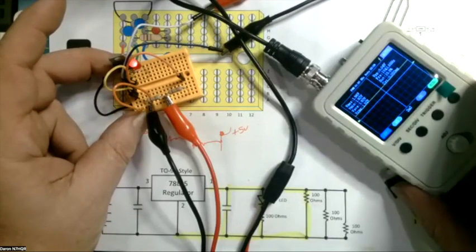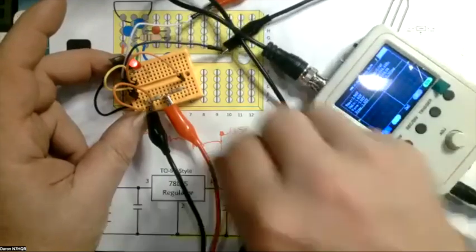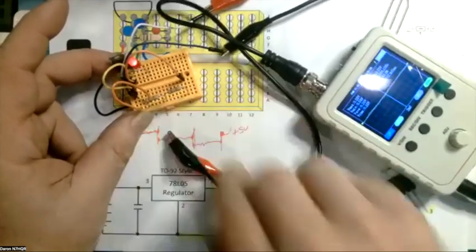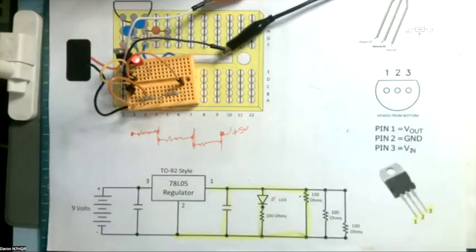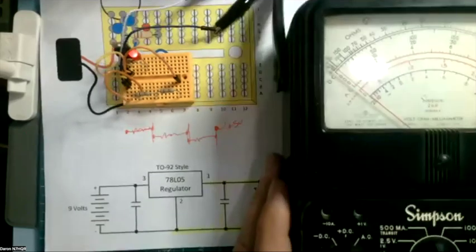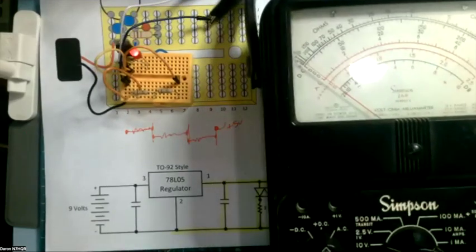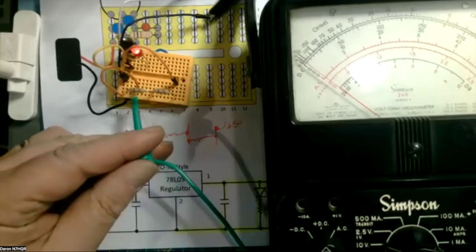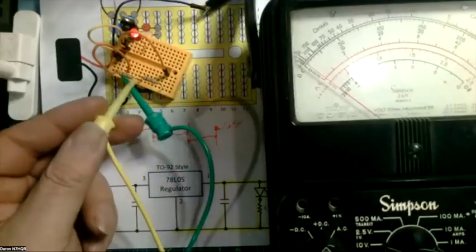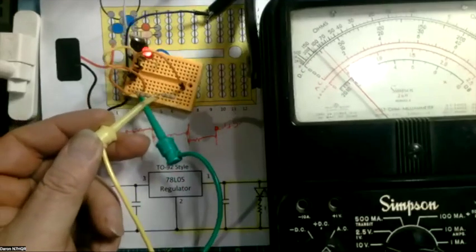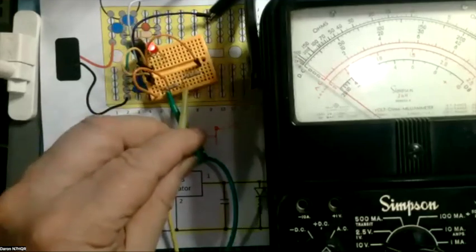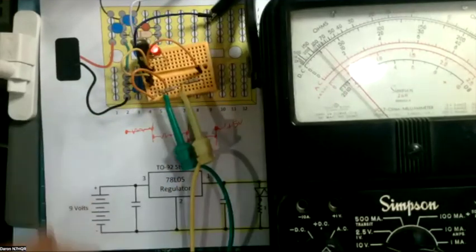Excellent. So when you have a device that has a high input impedance, it has little effect on the circuit. But if you have something like that old Simpson, which we all used to use, and yeah, we've got at least one person who still does, it can grievously affect the voltage that you're reading if you're not aware of what's happening. I think my Simpson is a 50,000 ohms per volt. Well, that's one very sensitive voltmeter.